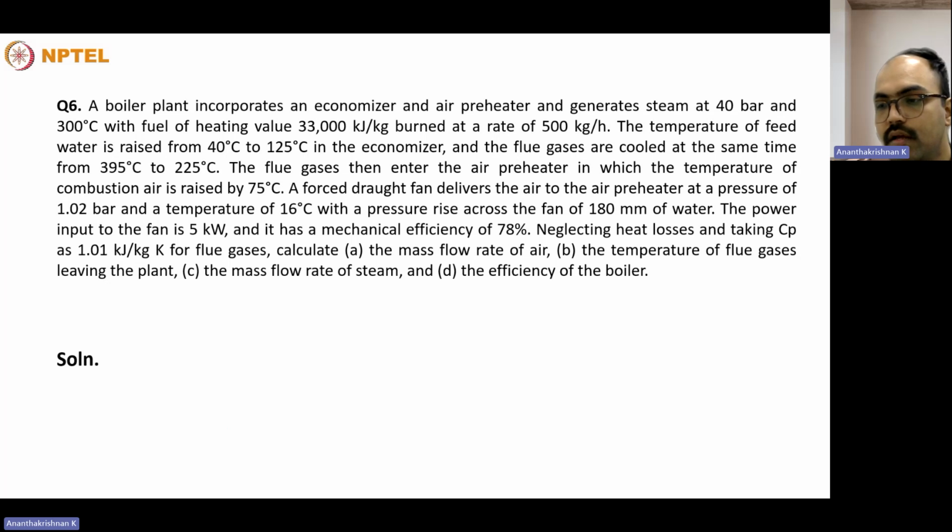So the air preheater heats the air before it enters the boiler, to reduce the gap between the already combusted fuel flue gases and the air. The difference in temperature can actually result in a reduction in the efficiency of the boiler. So to prevent that, we preheat the incoming air using the flue gases that will be released from the boiler.